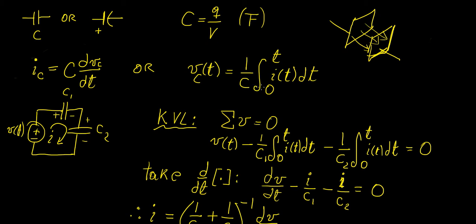Now, what we're really interested in knowing is, how do capacitors add in a circuit? Can we find such a thing as a total or an equivalent capacitance? And the fact is we can, and we can use Kirchhoff's laws to find that. So suppose we have a circuit like this with two capacitors in series, and we want to find out what's the total current across the circuit. We can use KVL because it's a closed loop of current. And so that KVL tells us that the sum of the voltages or the potential drops is going to be equal to 0. Now, we're going to use the same convention.